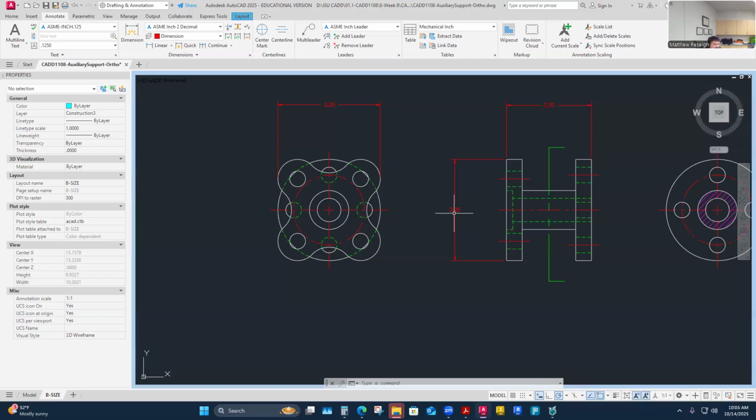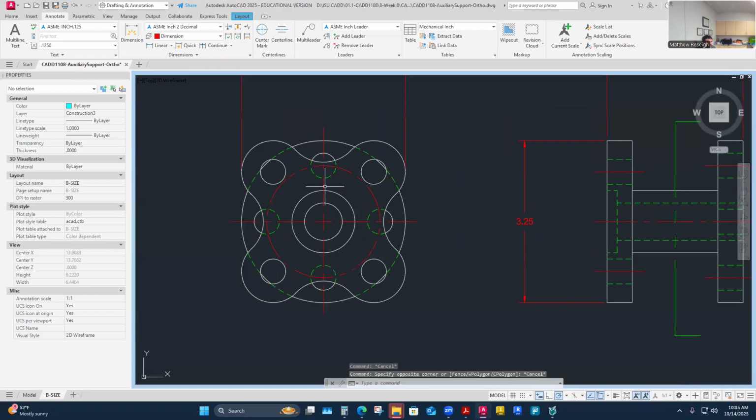I'm probably going to place my controls on the center lines. So in the front view, I have these vertical and horizontal center lines, my center marks that I placed. I feel like those are probably the control for this X, because on a weird shape part like this, center is our best control.